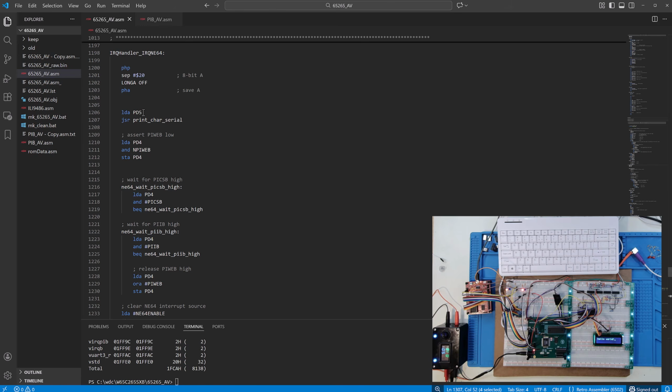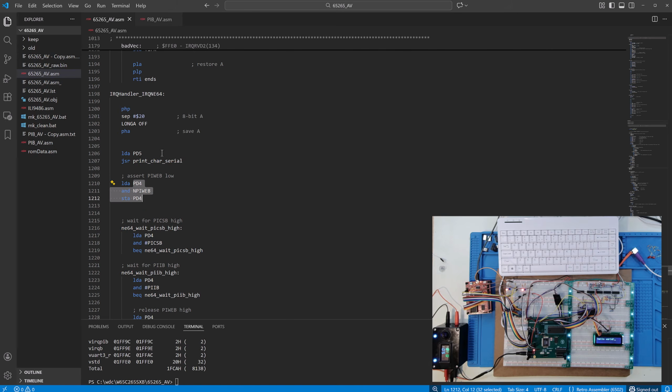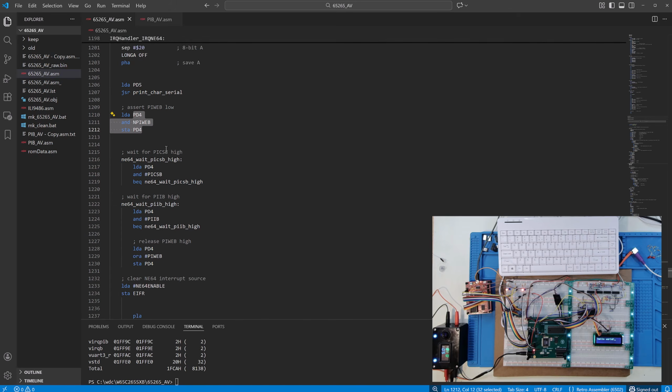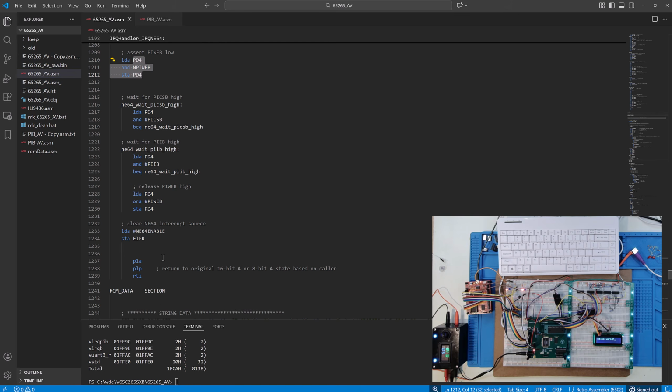And the first thing I'm going to do is when I get this interrupt, that means I know the master's already indicated to me, hey, I've got data on the data bus for you, go get it. Again, when I say data bus, that's port 5 interconnected between the two microcontrollers. Go read it, print it out to the slave serial console, toggle this line here that is, what was it, 43, bring that low. And then at that point, it just simply waits for the master to take its lines back up high. And then I can basically get out of here, clear the interrupt on the way out.